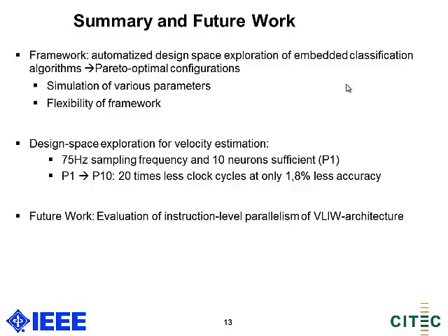We have simulated various parameters, and our framework is very flexible because you can extend it using new features, inserting a new classifier, or even exchanging the instruction set simulator of the microprocessor, and therefore simulating a completely new hardware platform with some functional units like a hardware multiplier.